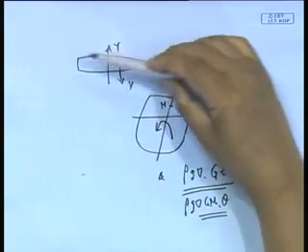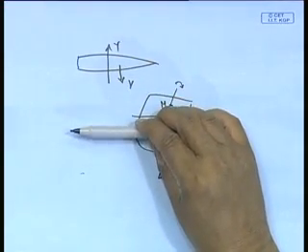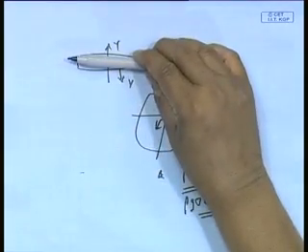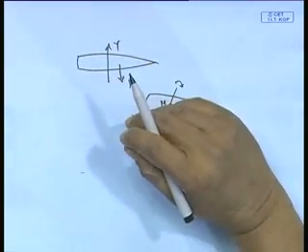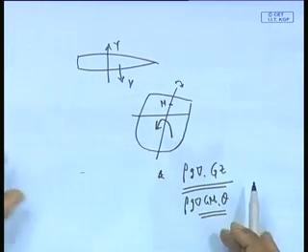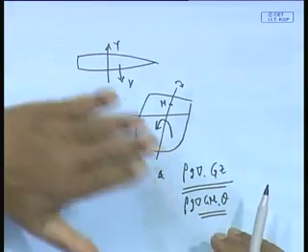So, if I want to give a V here, once again the hull force that gets created will try to bring it back, because the force is on the other side. The tendency of the force is to make V smaller and smaller, just like here the tendency of the moment would be to make theta small, so that theta becomes 0 and the moment becomes 0. As the ship turns, theta will become progressively 0, and therefore the moment will also become 0. So we call it stabilizing.